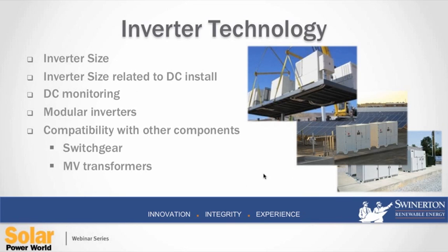Looking at DC to AC ratios, like Jeff mentioned, there is a strong push by EPCs to increase that as much as we can. When we look at different requirements coming from whether it be developers or the utilities themselves, we look at the technology having the capabilities of doing some monitoring or SCADA-related data flow further out into the field, whether it be DC inputs, combiner boxes. We even have string level monitoring on some of our projects. That's an option we look at.